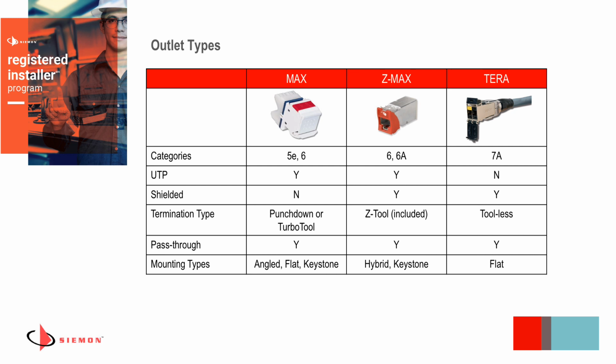So it's a non-impact type of tool. It's more of a lacing the conductors in place, trimming them, and then putting into the Z tool and kind of squeezing it with your thumb to terminate. So a little bit different than a regular punch down, but certainly much more installer friendly and much easier on the fingers compared to a punch down style outlet.